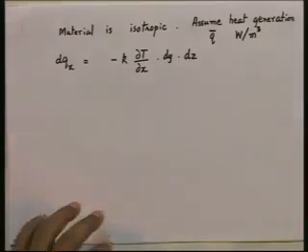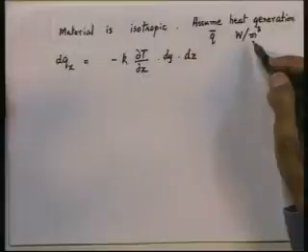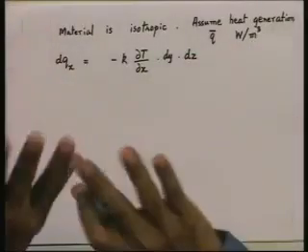All right. We will use the symbol Q bar for the rate at which heat is being generated per unit volume of the solid. Q bar may be a constant if heat is being generated uniformly. Q bar may also vary from place to place, in which case it will be a function of x, y, z. Q bar could also vary with time, in which case it could be a function of x, y, z and time. Whatever it is, it will be some specified function, or it will be specified to be a constant. So, let us assume there is some heat also being generated.